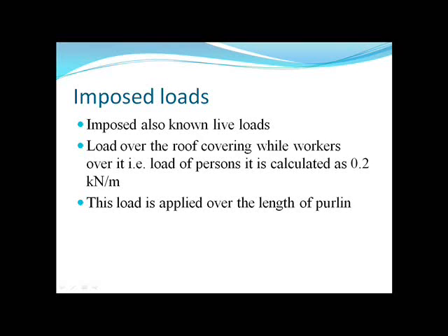And the imposed loads or live loads on floor shall comprise of all loads other than dead loads. And we have taken the live loads on this structure as 0.2 kN per meter. This is applied over the length of the purlin.